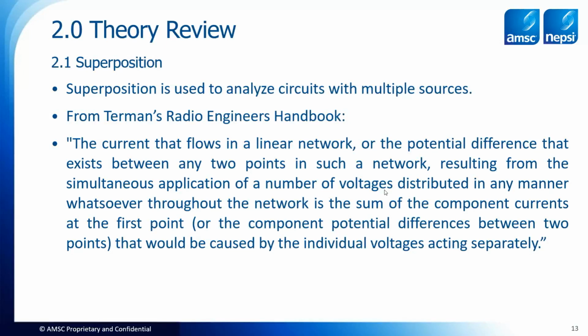I'm not going to read this complete definition out of Terman's Radio Engineer's Handbook, but the key thing it states is that at any point in an electrical network, you can calculate the resultant voltage or current at one point due to multiple sources by doing an analysis multiple times, each one with an individual source.